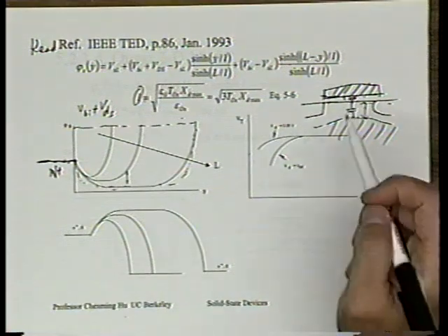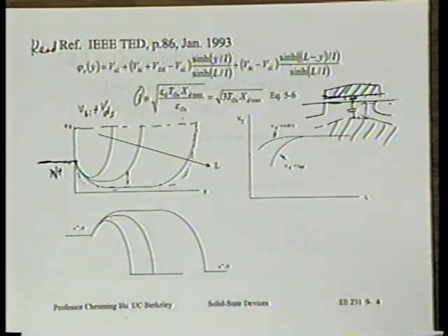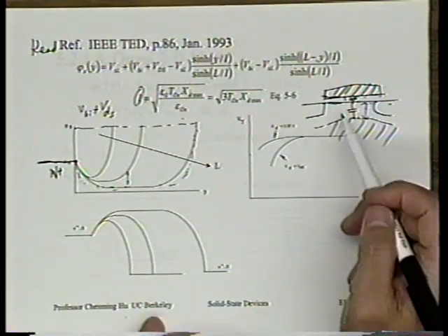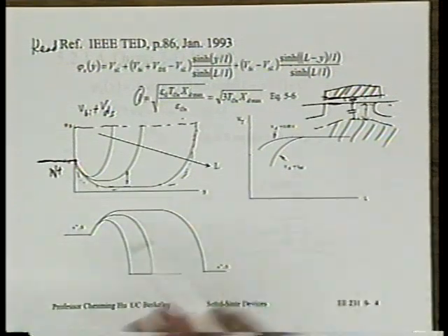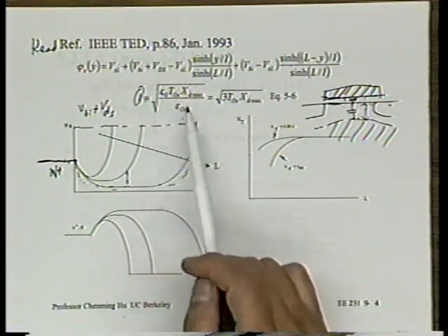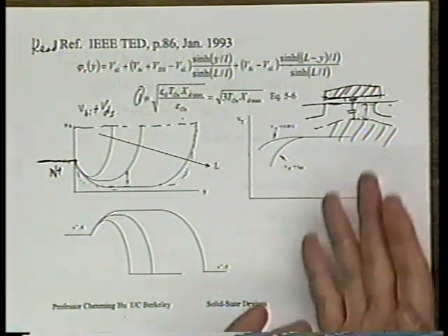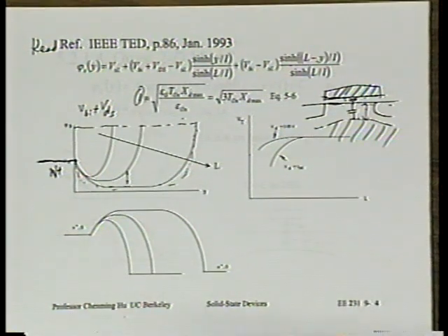Can you see that the impact of these top and bottom gates on the potential at the surface is basically the same, roughly the same? You have two gates that are equally separated from this interface. Why shouldn't these two gates have the same impact on the surface potential? You see what I'm saying? It makes sense, these two appear in a symmetrical way. So when you see this, you get a lot of confidence that the model really makes sense. You start with Gauss's law, didn't consider all these considerations, and yet the results tell you things that really make sense.